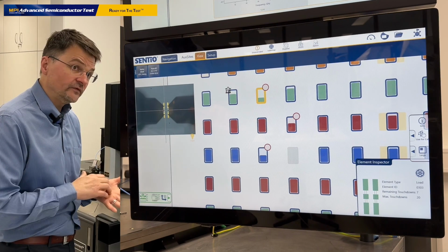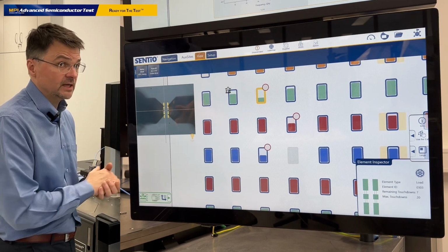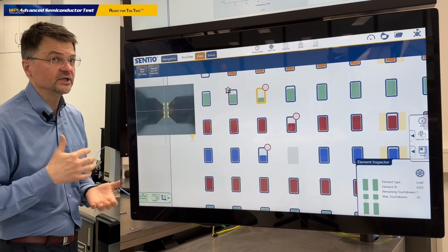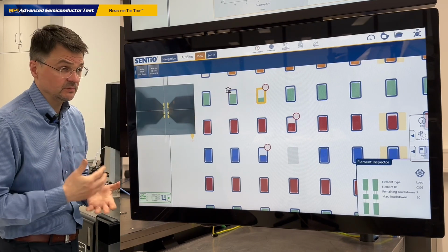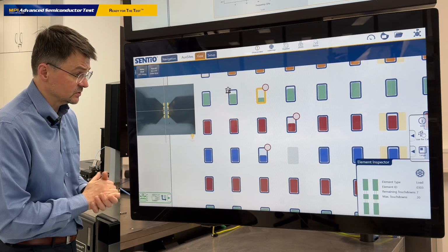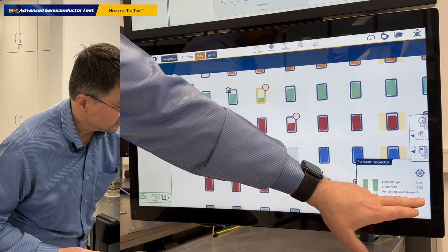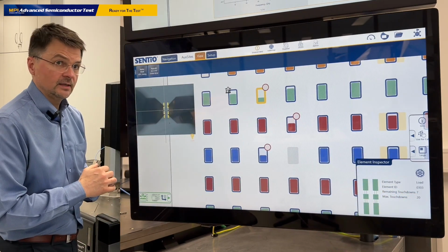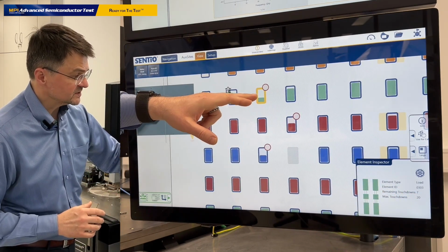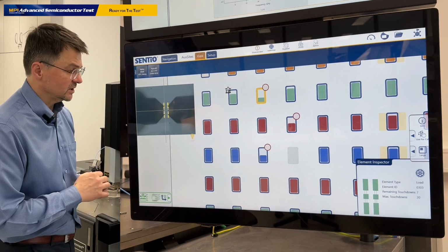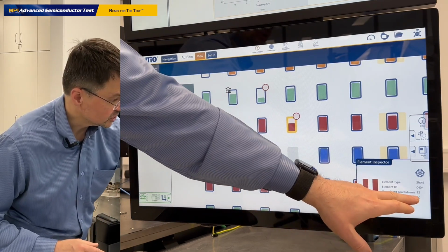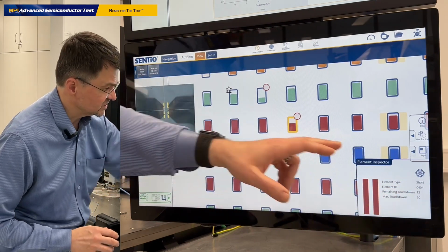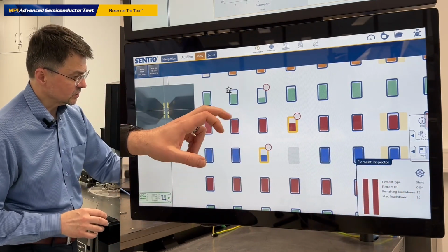When we use the soft contact feature on MPI machines, you can use the calibration substrate for more than 100 touchdowns. And we did these experiments, even more than 500 touchdowns is applicable. So out of 20 available touchdowns, we have only 7 touchdowns left, which means that over 50% of the lifetime of the standard is used. Same for the short. The short was used 8 times, so 12 touchdowns left, and also 12 touchdowns of this open element.